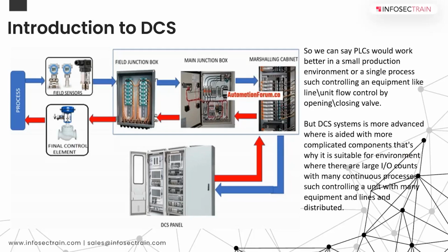DCS is basically for monitoring purposes. The same DCS, when used for a different purpose like fire and gas or emergency shutdown, or ESD, will also do some control actions. Of course, here also there is control action, I don't say it is not, but we do have some critical shutdown systems which are kept separate from the DCS.